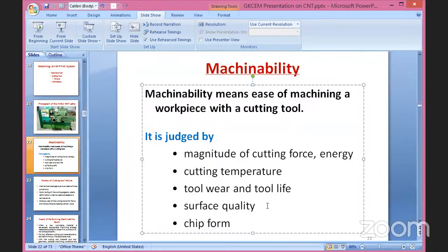Sometimes we require surface finish, sometimes we require high surface roughness also. Another very important thing here is surface integrity. On the surface, there should not be any crack. Below the surface, there should not be any crack, nor tensile residual stress. From outside, it can look very good, but inside, if some crack is sitting or some tensile residual stress is there, then upon severe loading, maybe impact loading, maybe reversible loading, this item can start cracking. This crack can propagate to the surface, and ultimately it can lead to fatal failure. So that also should not be there.